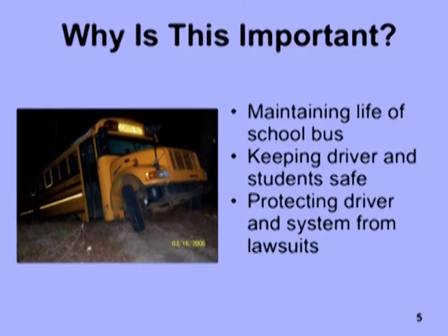What do you think the driver of this school bus failed to do? The driver of this bus failed to set the parking brake and did not properly secure the bus at the completion of a trip. As you can see by viewing this picture, omitting one simple step for securing your bus at the end of a route trip can create a serious problem for you and your school system.